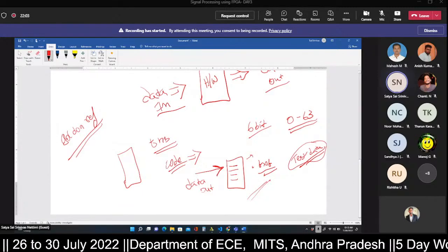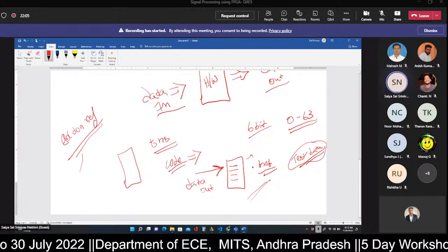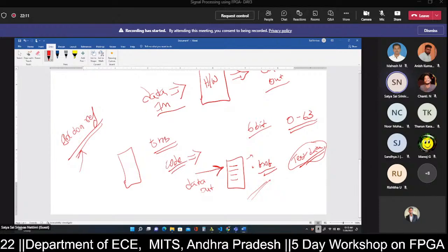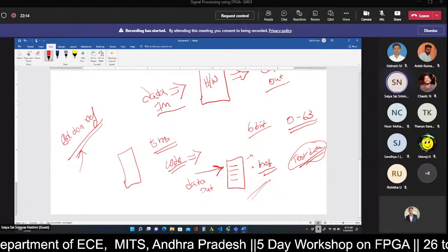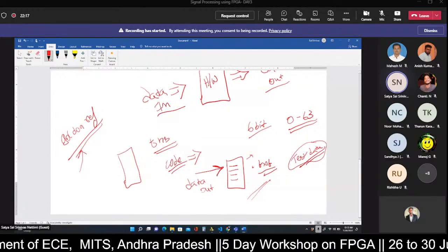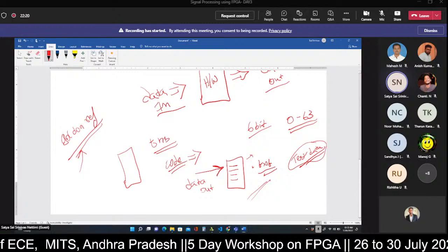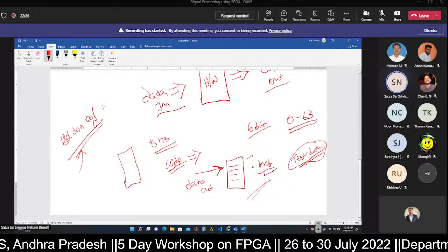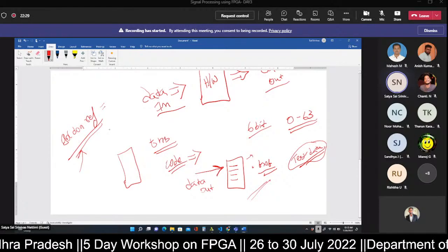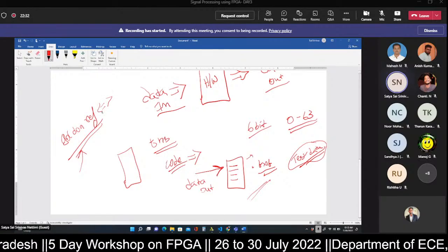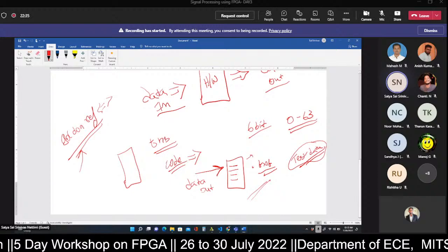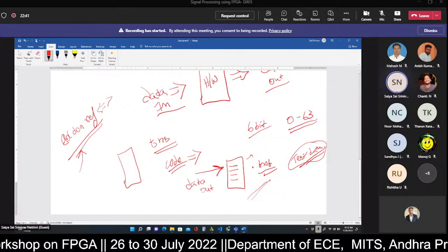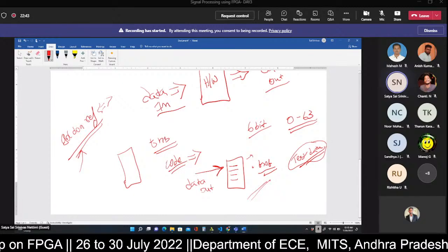So what you have to do is compare the data which your hardware has generated with the golden reference data. That is the actual data that you have obtained by processing that algorithm or process in a scientific programming language using the input data. The obtained hardware data is compared with the golden reference data, and it should be equal. Only then can you say that whatever functionality you have mapped into the hardware, the algorithm is performing in the same way as in the software.